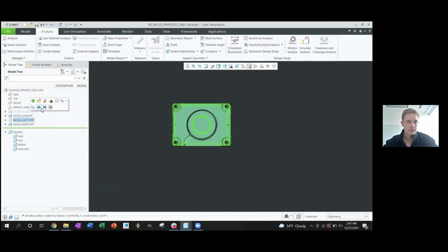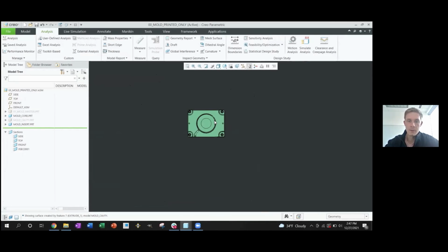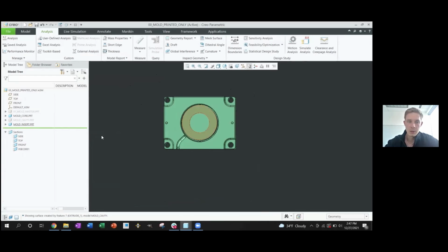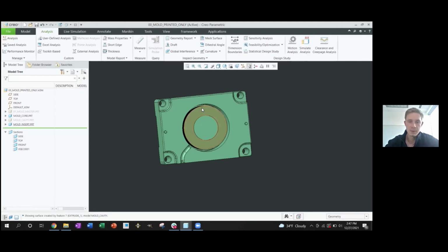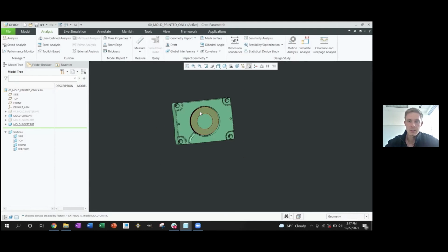At this point, we have our core and cavity block. They're designed. This is now a functioning mold. We're going to touch on our ejection strategy here. For this part itself, it's not a straight open and close tool, so we're not really going to bother with ejector pins on this particular part. What our strategy is going to be, and I've talked about this a couple times already, is we're going to do a hand ejection process. Since we're going to be ejecting the part off of this core by hand, we're going to turn this into a fully manual process here.